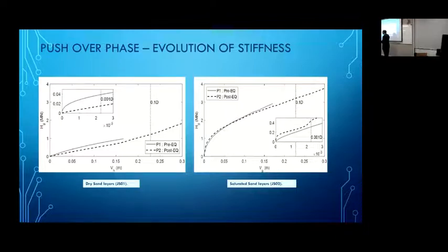But what's interesting is this stiffness. If I take a dry sand sample, because a lot of people who design these things imagine that these things can be fully drained, and if you look at the PISA project and other things that Imperial have done, they imagine it to be drained material. Of course, soil drained and undrained makes a big difference.